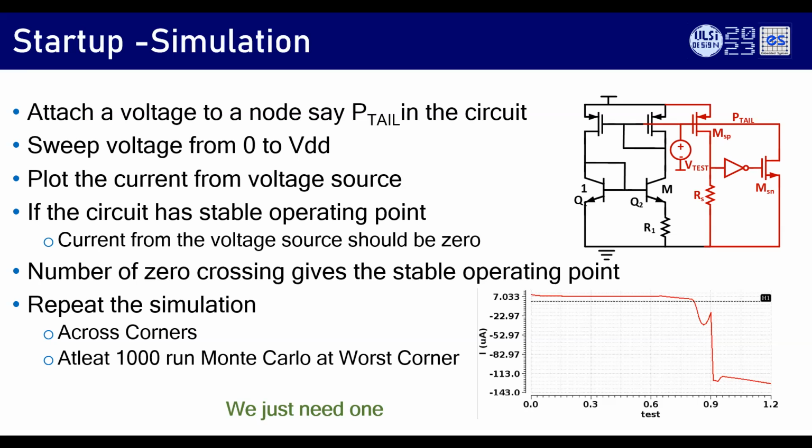It's hard to answer, but my guess would be that maybe you are not disabling the startup. When the bandgap turns on completely, your startup should be turned off. If that is not happening, then what you're saying can happen. Or, I need to check before answering. I don't know. It's hard to answer.